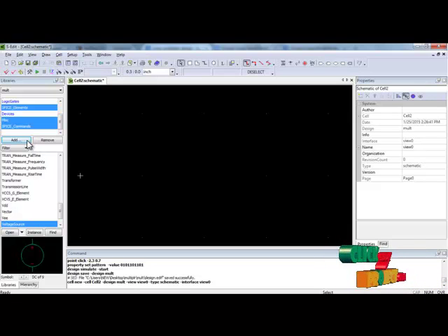While you press add, it leads you to a window menu, where you can locate the library file where you have stored it. From that location, you can select all the components you need for your CMOS design. After designing this cell, you can save the design, and while you press run, it leads to T-Spice.